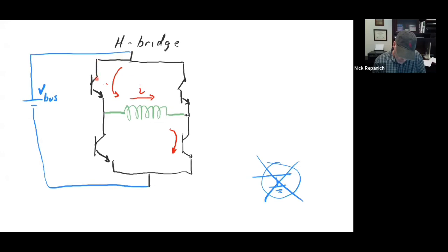We're closing that switch. That's a transistor. That's a switch. We went through the winding, current flow that way, and then I bring it all the way back. Get in that habit of showing that circuit, okay? So the key, though, is that gave it positive north-south energized to the winding, and that makes the motor go that way.